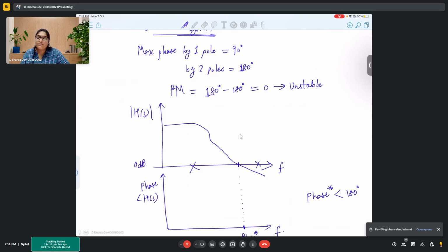So by dominant, do we mean it should be quite far away? No, no, it's the closest pole. The first pole is the dominant pole. Because after that you start seeing a drop in your gain, right? So your bandwidth and everything is more or less related to the dominant pole. So how far should it be from the crossover frequency?